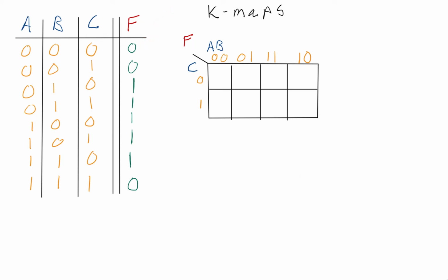Well, in that lecture, I also said it was really important to minimize the number of gates that we use, because AND gates, OR gates, and NOT gates all take up space on our chip and they use transistors. And the more transistors you use, the bigger chip you have to make. Also, the slower it becomes. Each gate makes the circuit run a little bit slower, so your CPU will run a little bit slower if we have more gates. They'll also use more electricity.